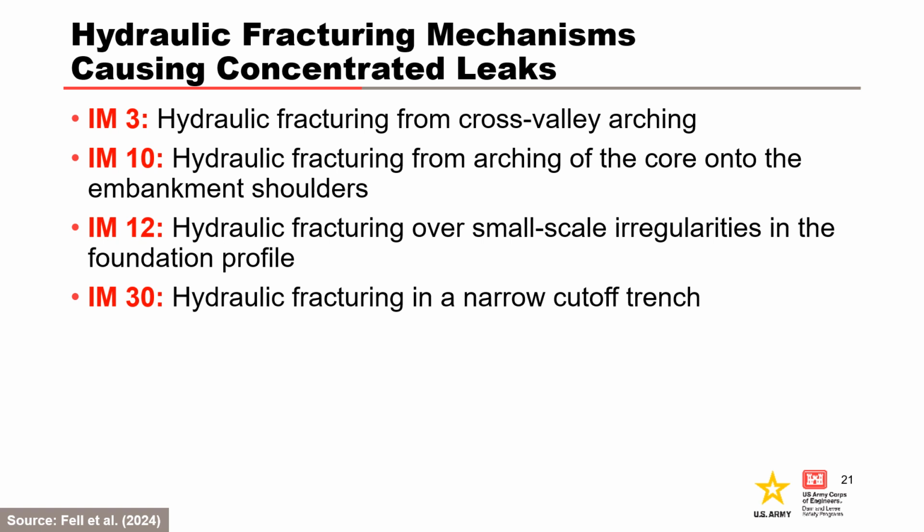Hydraulic fracturing mechanisms are listed on this slide. Hydraulic fracture is more likely to occur on first filling or during large rises in the reservoir level above the pool of record. It is unlikely to occur under normal operating reservoir levels.